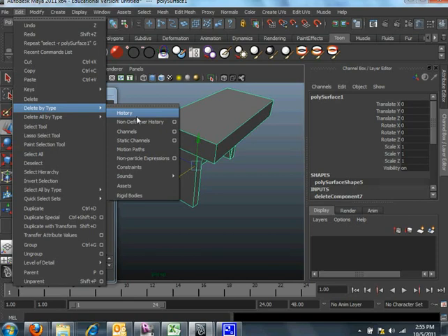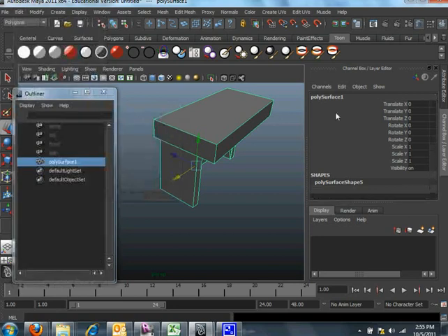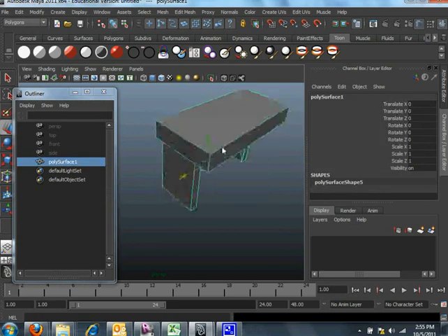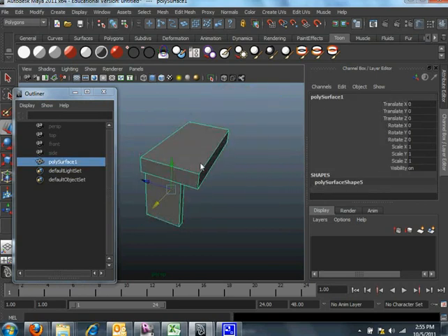It's just like Grasshopper. But the problem is every single action, if you remember, the file will get bigger, getting slower and slower. So clear the history is like I compress all the actions into the mesh, into the XYZ location of the points. You cannot go back after this point, but the file is more, I would say, efficient to work with. So I delete history. You see all the history nodes is gone. You got a pretty clean model. I like it. Then I will do more detail.